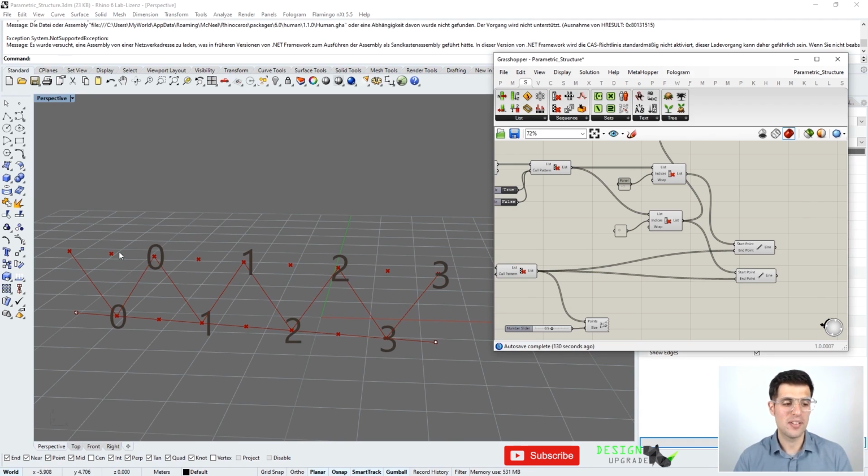It would be very easy to just connect the endpoints of our chords here, but if we were going to analyze this structure, that probably wouldn't work very well with the calculation program. So instead, we're going to define different segments between the nodes of the lower chord and upper chord.